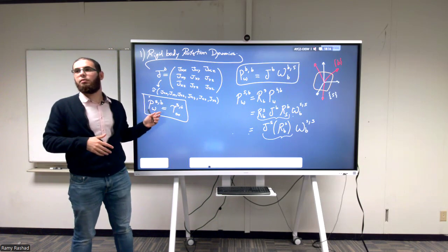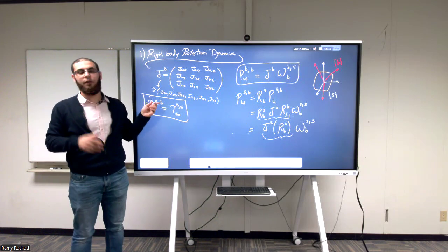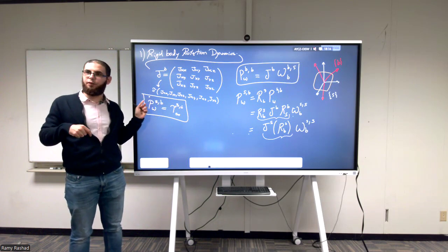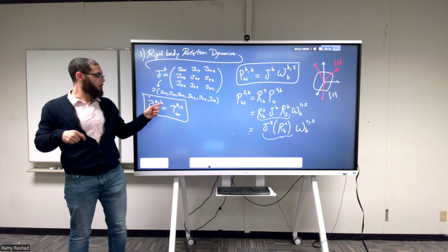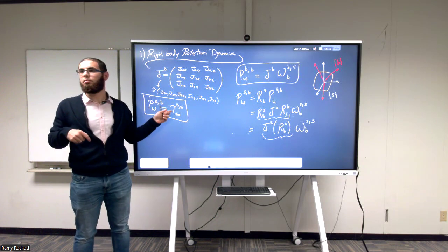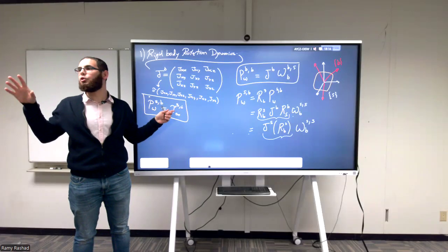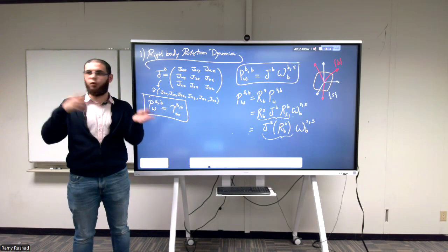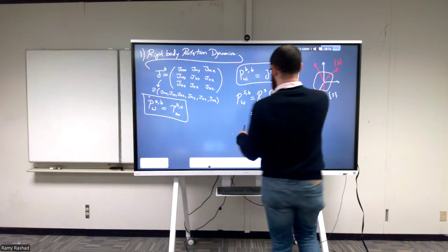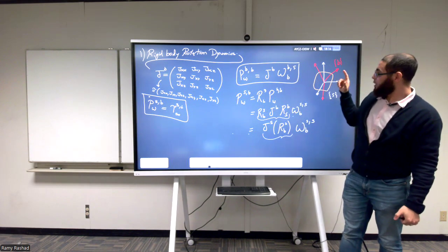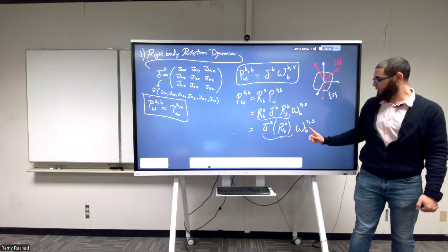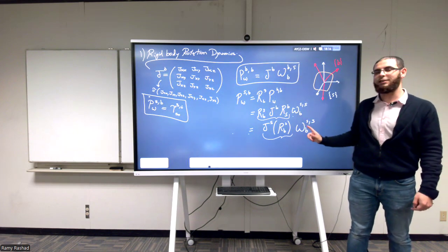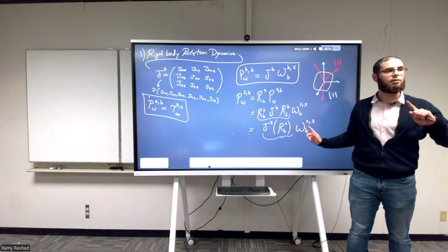Newton's law in general says that the rate of change of the total momentum, the generalized momentum variable, expressed in the stationary frame, will be equal to all of the applied wrenches. We're going to be using W to correspond to the combination of linear forces and angular forces, which is torques and forces. When we use this term, how do we represent the velocity or the twist from one frame to the other, going from this frame to that frame?